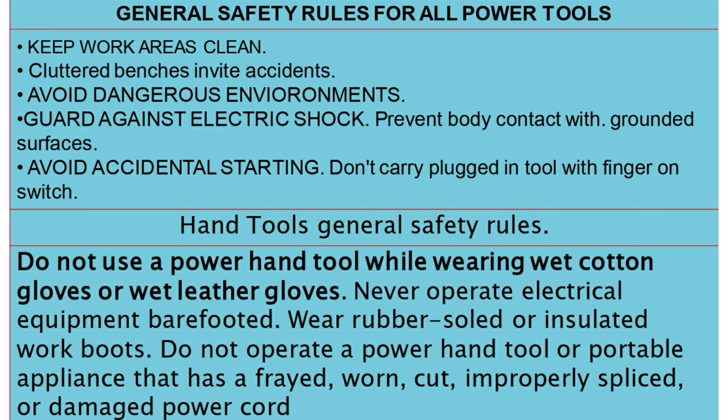General safety rules for all power tools: keep work areas clean. Cluttered benches invite accidents. Avoid dangerous environments. Guard against electric shock. Prevent body contact with grounded surfaces. Avoid accidental starting. Don't carry a plugged-in tool with your finger on the switch.